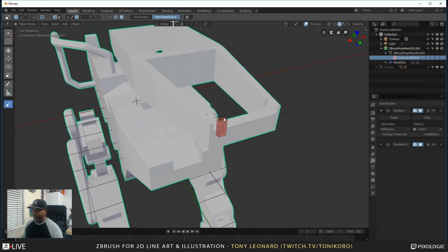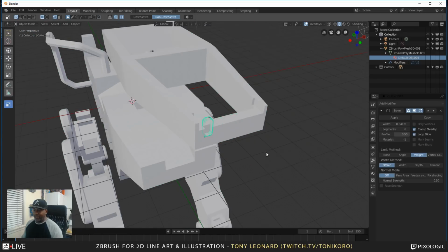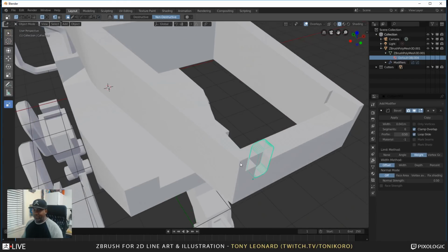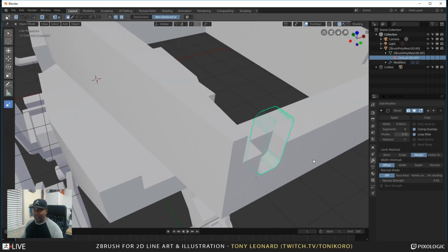And actually this time I'm going to right click to pause the shape. If I look in here very closely, what I'm going to do is take and do a bevel inside of this. So I can hit B on the keyboard and make a beveled cut into this. I'm only affecting this on one side, but as you can see, this live green box here, if I hold Shift and then click from that red box, basically it keeps the shape live. So I can come back anytime I want and just edit this shape.